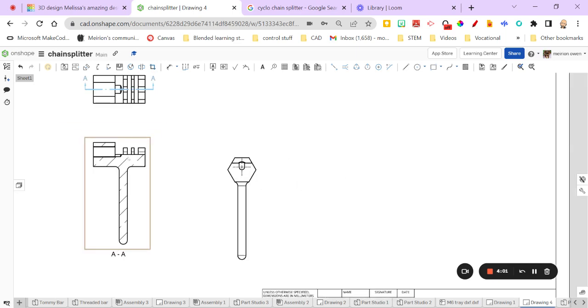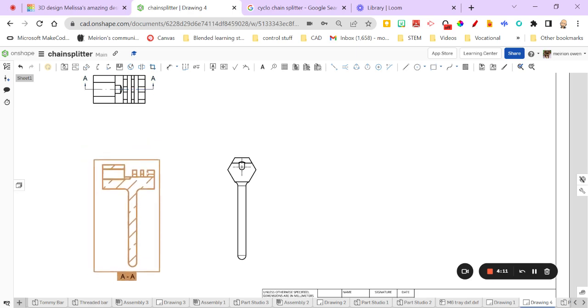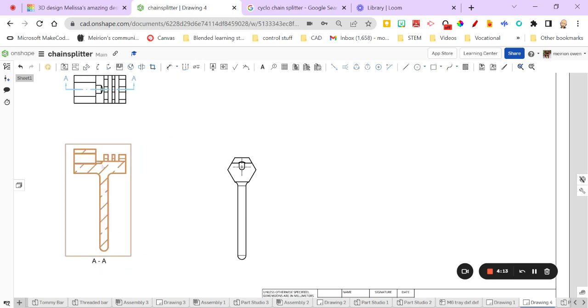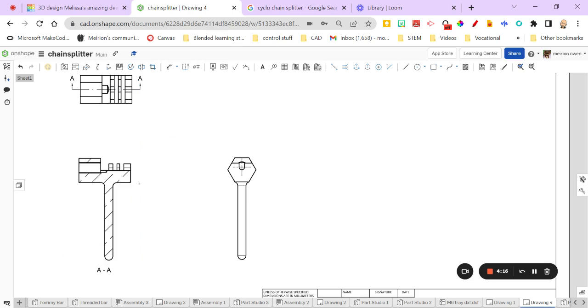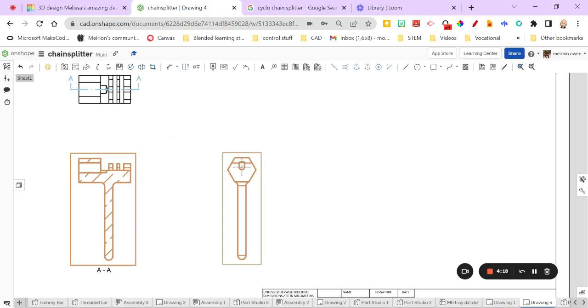It's just sliced through the middle and it's revealed some important information that I'm going to be able to show more clearly in that view. I'm not going to edit it just yet, but you will notice if I move that view now, the plan and the front elevation are related, but this end elevation's not. So I'm going to delete the end elevation. Oops, Control Z, I have two selected then. Click on that one and press delete there for this view.